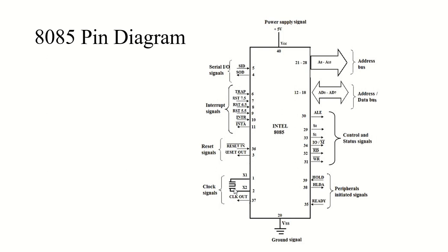First one is the carry flag. This flag is set whenever there has been a carry out of or borrow into the higher order bit of the result. The flag is used by the instructions that add and subtract multi-byte numbers, and rotate instructions can also isolate a bit of memory or a register by placing it in the carry flag. So it is one if there is a carry out of the most significant bit, and zero if there is no carry from my MSB.